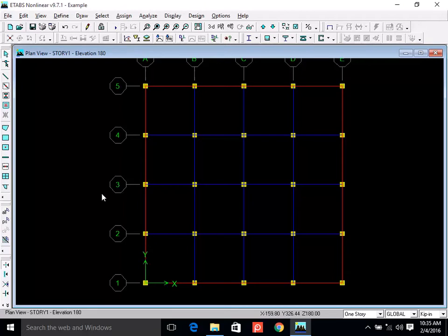You can display your structure by color to quickly identify whether you have used different sections or any section is different, in case you sometimes need it, because when you are designing a big structure there are so many different sizes. So just by looking at colors you can differentiate what beam is where, so you can pick your mistake sometime. Okay, how about the columns?